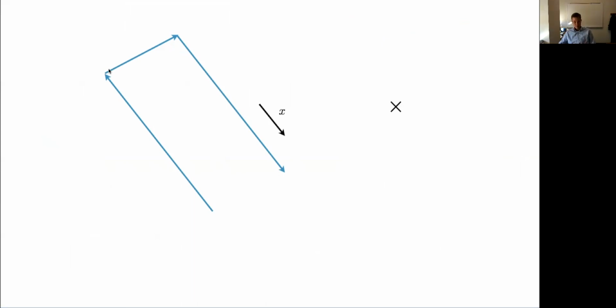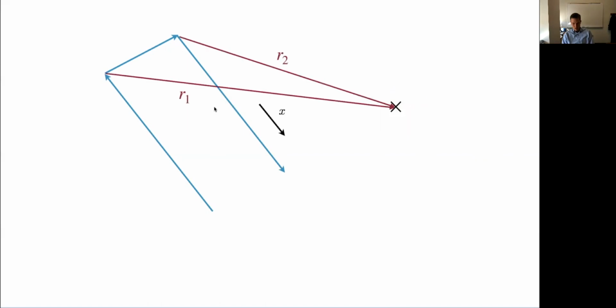So here's a picture of that. This is a generic horseshoe vortex. It's going to, as we've seen, continue with the same strength everywhere. And by our convention, we've defined it so these trailing vortices are aligned in the x direction. And I need to evaluate my velocity at some arbitrary location, control point x, which is some other location. Turns out these two vectors will be important in this derivation. R1 is the distance from the corner of this horseshoe vortex to that arbitrary location. R2 is the distance from the other corner.